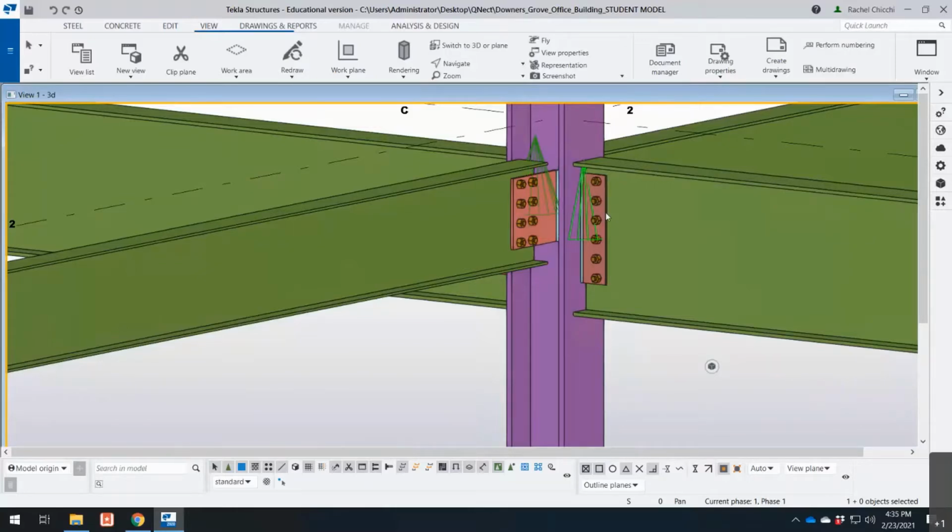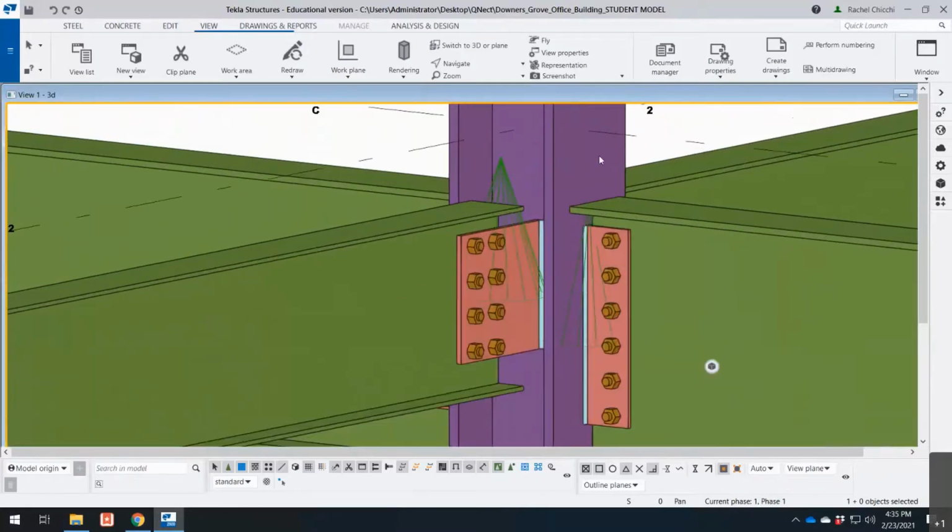When using a double angle or an end plate connection, we are limited by the width of the column flange. This is our connection surface, and we can't extend beyond that. So we need to make sure that whatever is needed with regards to the angle connection, the bolts and the weld, that they have enough edge distance to be able to be a suitable connection. When we had the girder as a support, the girder had a long length, and we really didn't run into this issue of having a limited width to our support.